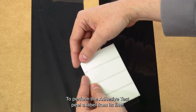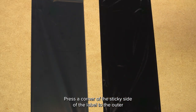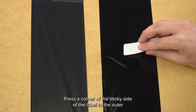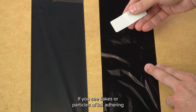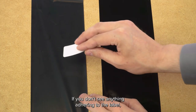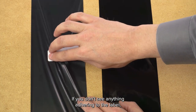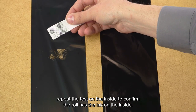To perform the adhesive test, peel a label from its liner. Press a corner of the sticky side of the label to the outer surface of the roll of ribbon and peel it off. If you see flakes or particles of ink adhering to the label, you know the ribbon is coated on the outside. If you don't see anything adhering to the label, repeat the test on the inside to confirm the roll has the ink on the inside.